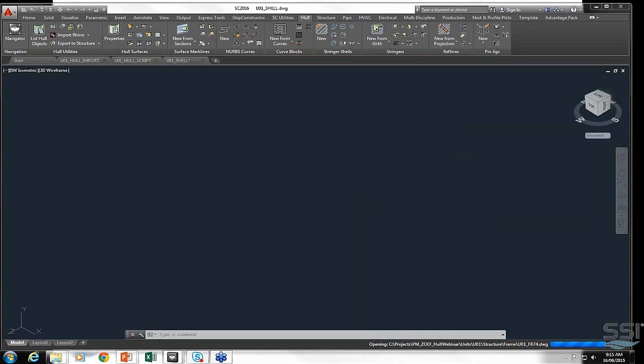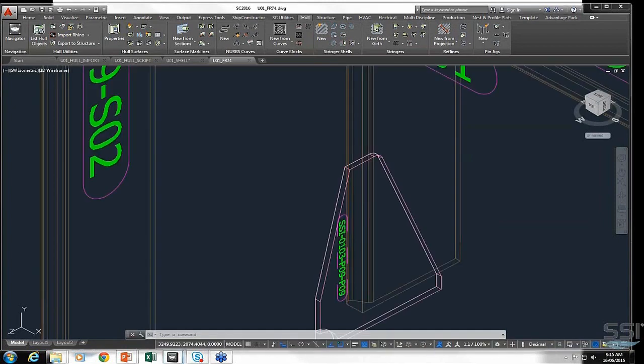Okay, while that's happening, so I misunderstood the question. There was a question of how you add the stringer to the shell plate part. So that's actually in Hull. The way that it was added was we produced, you can do it based on girthing, projections, polylines. You set up where you want those lines to be, and then the stringers are produced from those lines that you create.